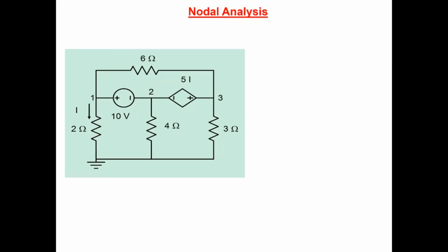We could have done this problem in an alternative way. In a circuit like this, we were given this node as a ground. But note that it's only a reference. Even though it's written ground here, we can choose the reference any way we want during the analysis, right? So temporarily, these are all the 4 nodes here, and we can forget about this ground node and choose whichever node we want as reference, as 0.